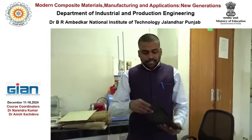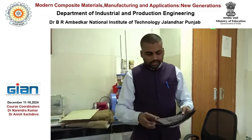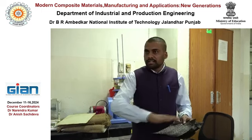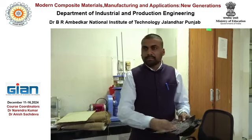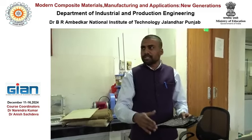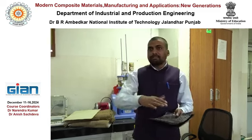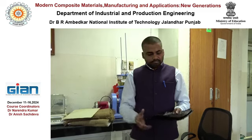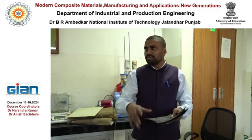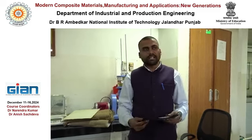So suppose we have to make a composite with 4 layers of fabric. What we are doing is taking one layer, applying a resin, epoxy resin, for example, by hand, then putting a second layer on it, again applying the epoxy resin, then the third layer, fourth layer, like that. And we are applying some dead weight on it. Suppose you are curing at room temperature, then we simply keep it like this for around 24 hours. Generally resin is cured in 24 hours.